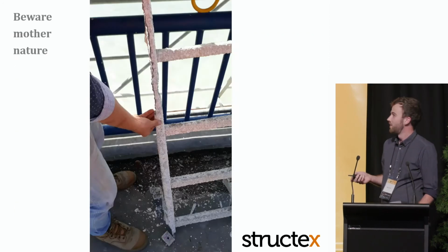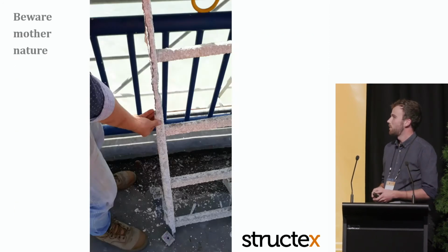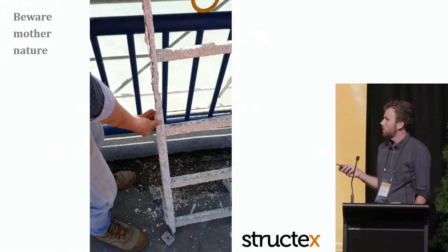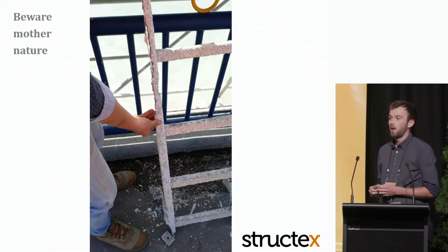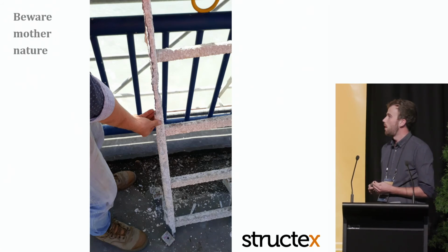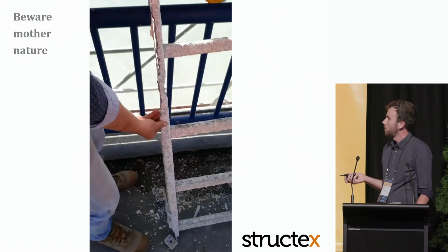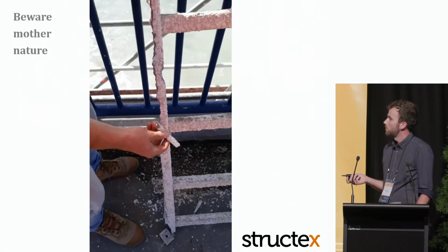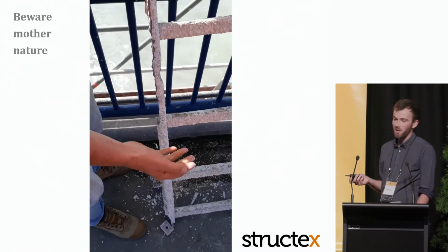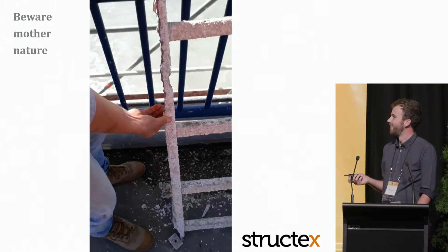All pieces were found. And then the final one, which is really just a lesson around bimetallic corrosion. This was one of the strangest things. This ladder here is an aluminium ladder, just like you'd get at Mitre 10, but it's been strapped to about 5 tonnes of steel in a corrosive environment for about 3 weeks. And it basically just breaks off. So we're tossing up whether to send that one back for a refund, but thought better of it.